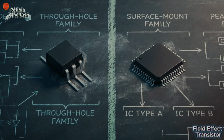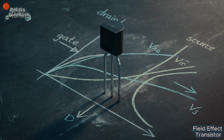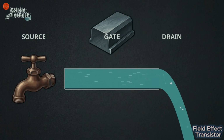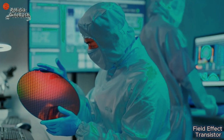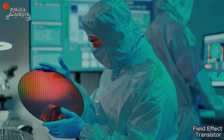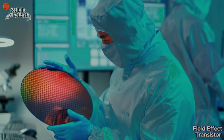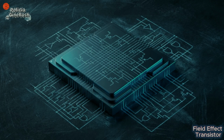If you look closely at these devices, you'll find they generally fall into two main families. The first is the JFET, or junction field effect transistor. This is the classic, basic iteration of our garden hose model. The second, and far more common today, is the MOSFET. MOSFET stands for metal oxide semiconductor field effect transistor. This is the upgraded standard required to run high-speed microprocessors.